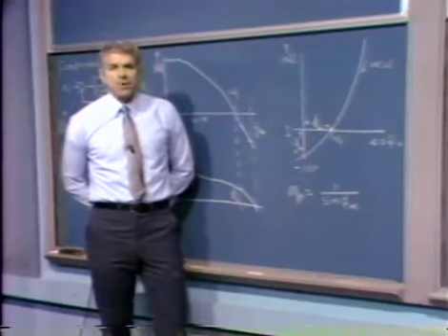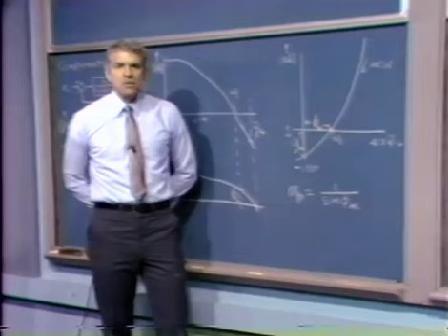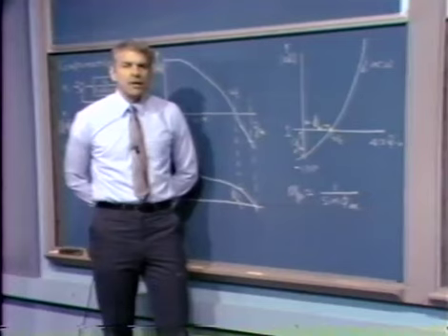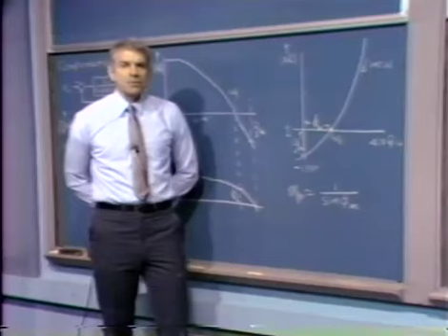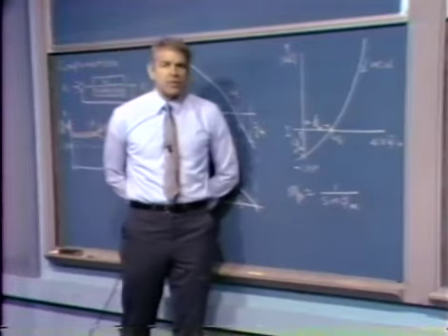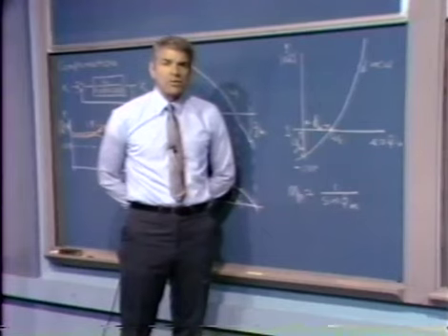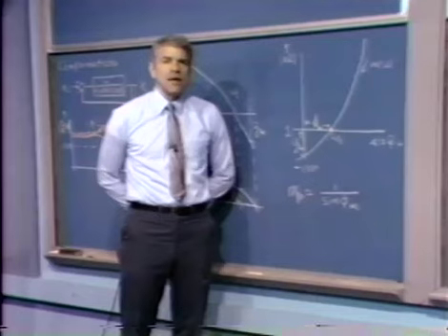We can go ahead and from the Bode plot determine, first of all, is the system stable? We can translate a Bode plot into Nyquist coordinates and determine rapidly if the system's stable. We're then able to go ahead and from the Bode plot, evaluate the crossover frequency very rapidly. We're able to determine the gain margin and see if it's, quote, enough. And then we're able to find the phase margin of our system. And those constructions are very rapid and give us remarkably good results when we ask about the performance of a feedback system. Once we know the phase margin and the crossover frequency, we can make excellent predictions about the closed loop response of the system.